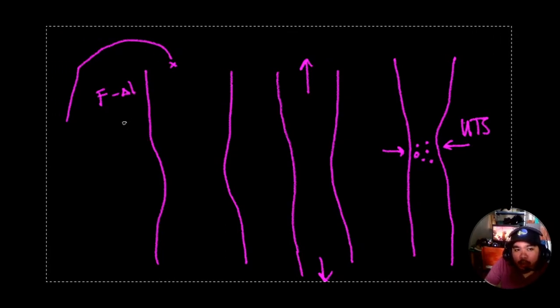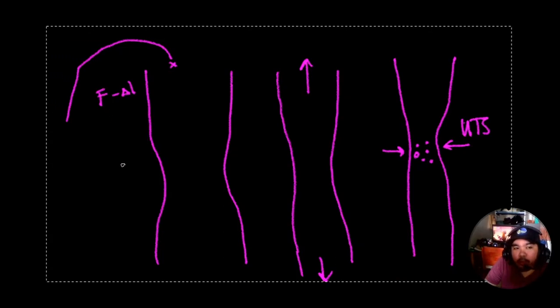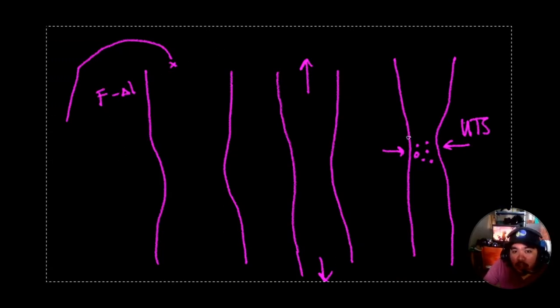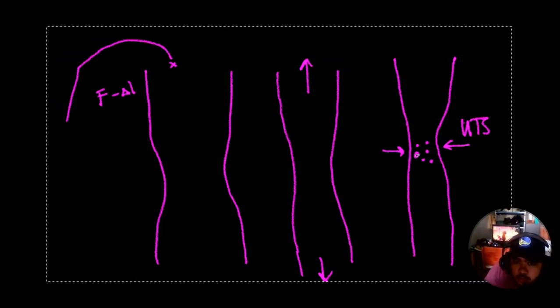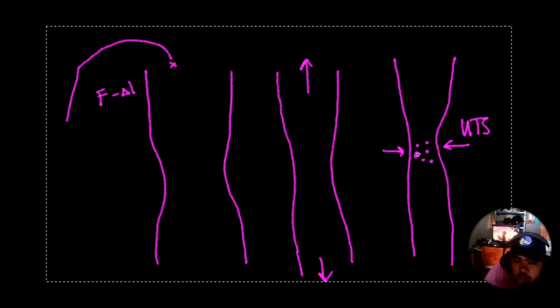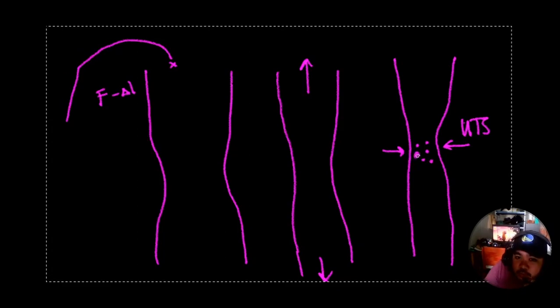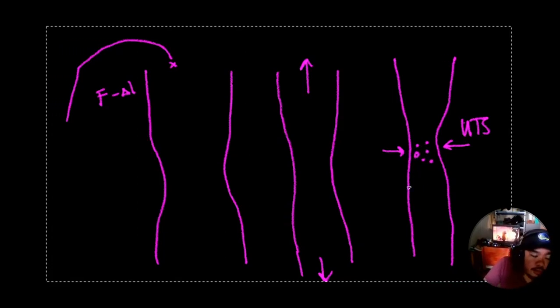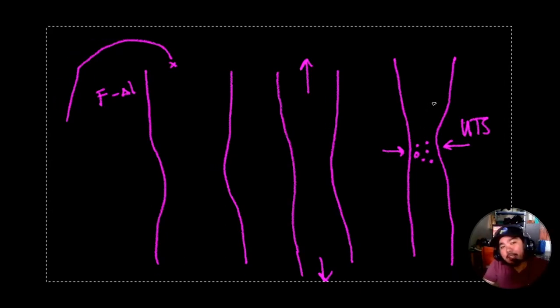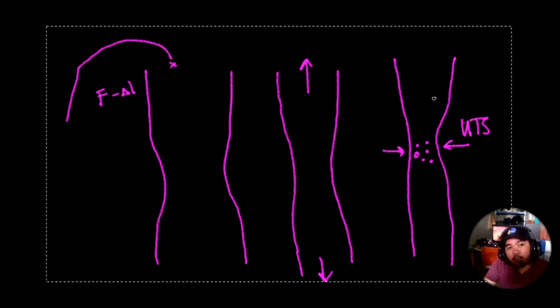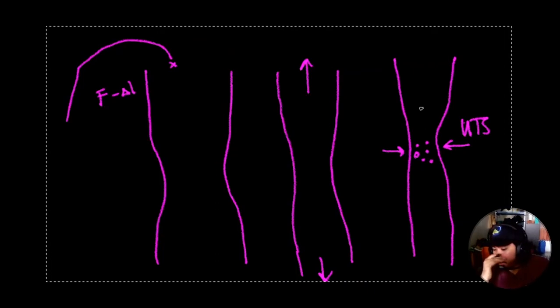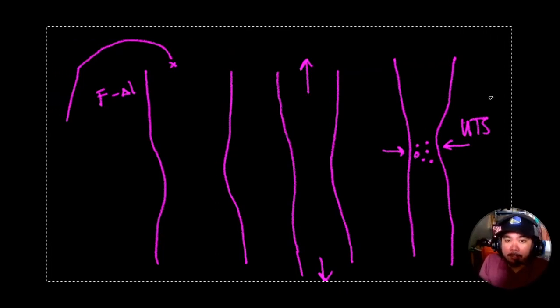So the force is lower dito sa portions na 'to kasi the area is getting smaller, and it actually takes lower amount of force to produce higher amount of stresses. Kasi if you notice, dito sa portions na 'to, when you have microvoids, nagkakaroon ka ng stress concentration, no? So the voids become stress concentrators. Therefore, it amplifies the amount of stress na available sa inyo with a lower amount of force value that is applied, no?